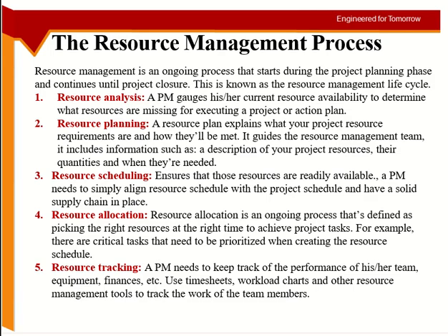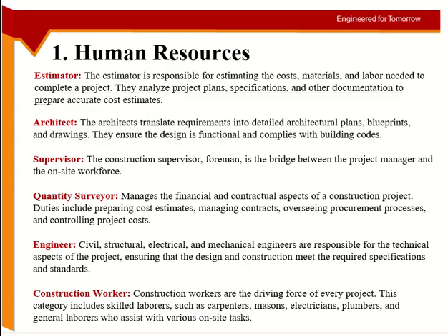And then you have resource tracking. Once the resource is on the site, you track and monitor. You look at the timesheets, you look at the quantities, you do quantity surveys, and so forth. For the equipment and labor, we have timesheets: when this guy came and when he left, and for how many hours this equipment was used. So these are the 5 steps. It starts from your analysis of the existing resources, then you see what you need and from where you will get it, then when you need it, then you deploy them, then you track them.